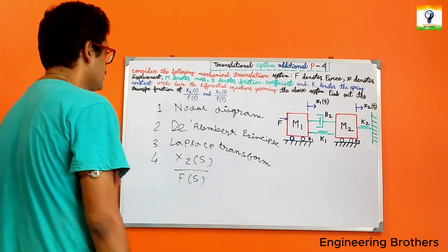So I do require to repeat this portion once again. First, you do require to identify which element has the direct connection with our displacement factors of our x1t, x2t. So first I have separately considered our nodes of our x1t, x2t over here, and let us identify which elements connect with our x1t. So you can see that with our x1t the M1 is directly associated over here. That is why I have included the M1.